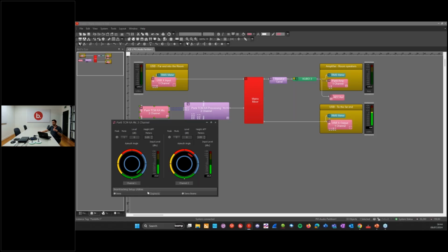And if I turn on the segment mode, if you can see my webcam at the moment, it's probably a bit smaller on the screen, but we can turn segments on and off, and you should see that with the LEDs disappearing from the front of the microphones. It may not be that easy to pick up on the cam. This is a nice utility so that when you're actually commissioning the system, enable it on the LEDs, and then you can very clearly see if I want to exclude this area behind me, you literally just turn the LEDs off in that orientation.